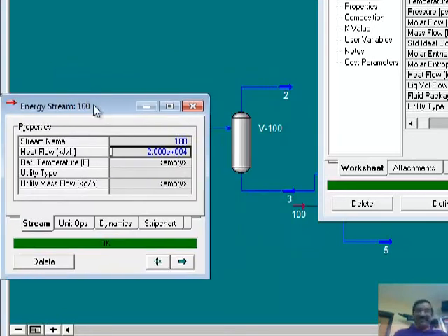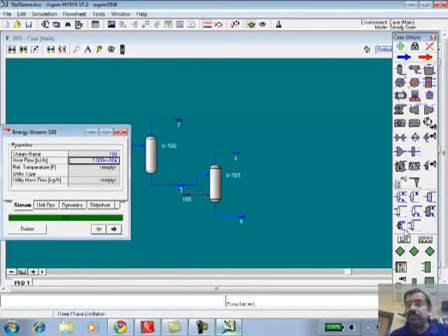We'll take some more time, but the question that we want to solve is, I want the molar flow rate to be 25, and you all have to be alert and guide me doing this because I'm flying blind now. So the goal is to get 25 moles per hour in the vapor product by adjusting the heat duty. We need to figure out how to do that. So I'm going to take the adjust block and put it there.